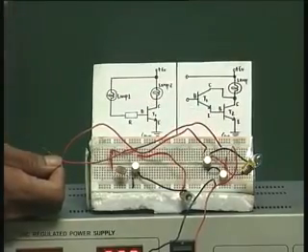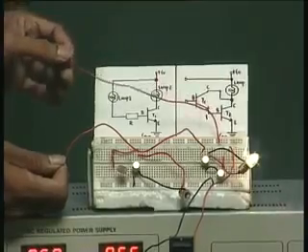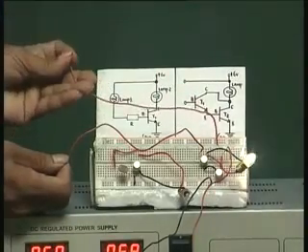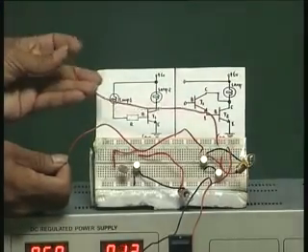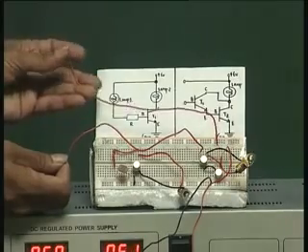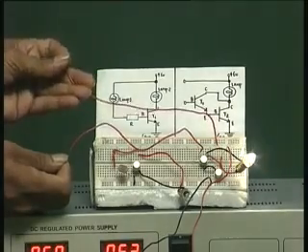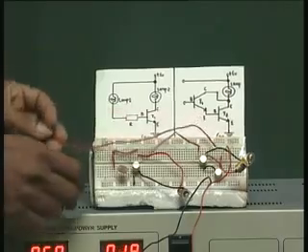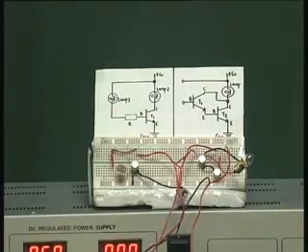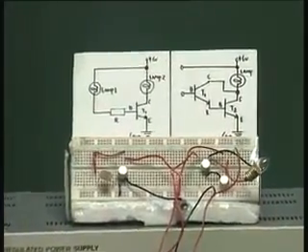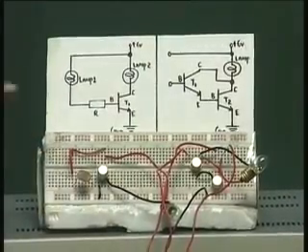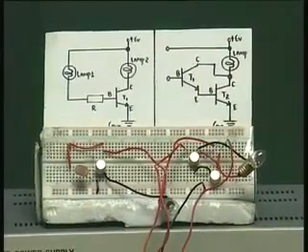When I remove my hand, it goes off. When I touch, again it comes on. When I remove, it goes. So you can see it is only because of my touching that you get the current there, and therefore you can immediately see the Darlington combination can help in amplification, in current amplification by a large extent, and that is what is shown here in the circuit.